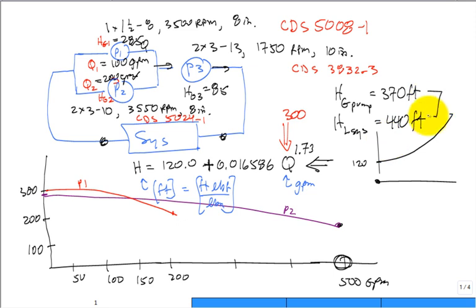So it's not balanced, is it? What's going to actually happen to this system? Is the flow going to be higher or is the flow going to be lower to balance it? So we need to decrease the flow, right? You think that the balanced flow will be lower than 300 GPM? How many people need more time to think about it? Or is it 300? Looks like 300. Okay, I'm going to tell you that we are not too far off. The final is 262 GPM.